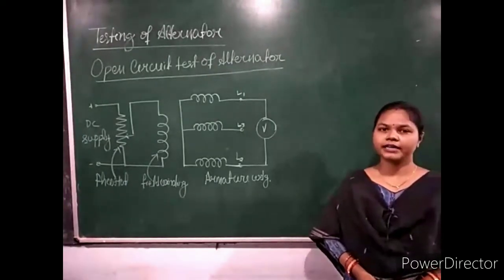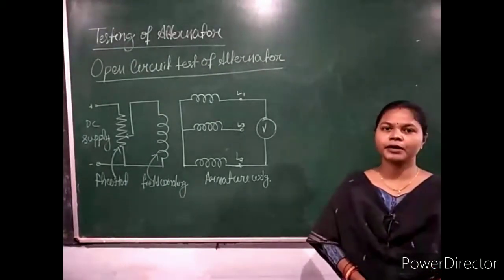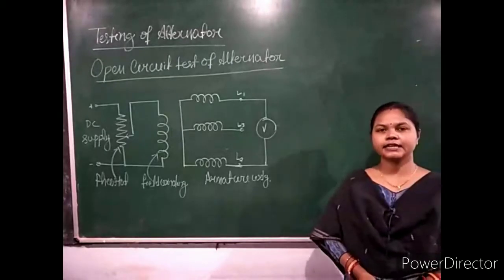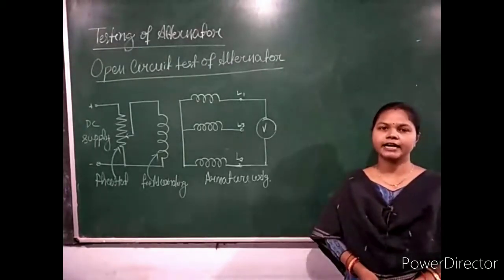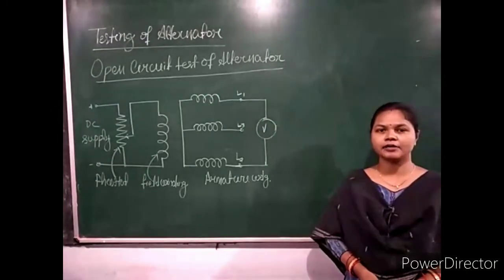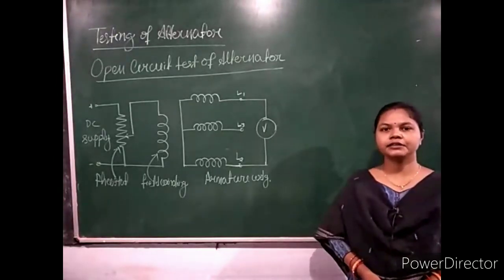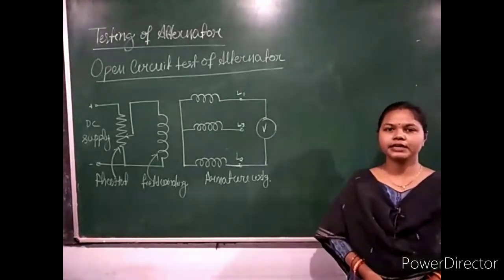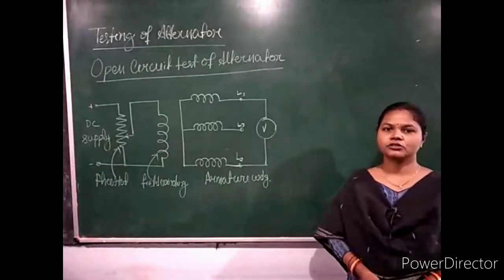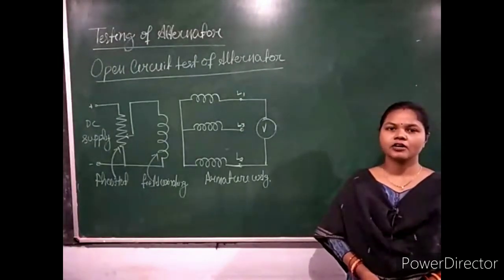So, what is the purpose of testing of an alternator? The open circuit test and short circuit test are performed to find the synchronous impedance of an alternator to determine voltage regulation. So, let us first start with the open circuit test of an alternator.